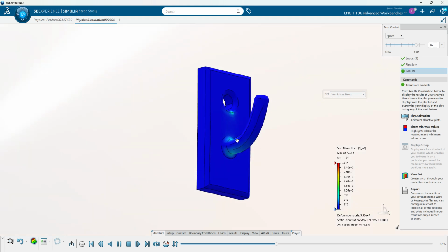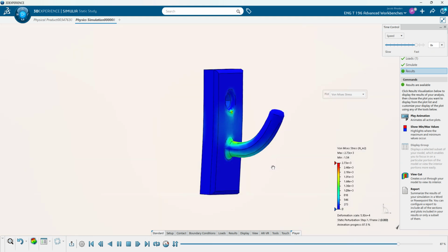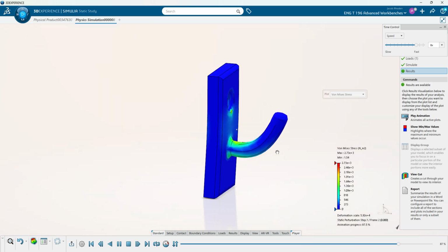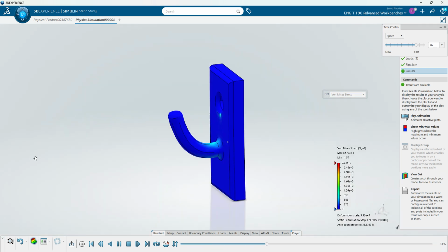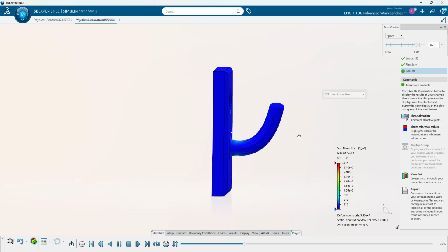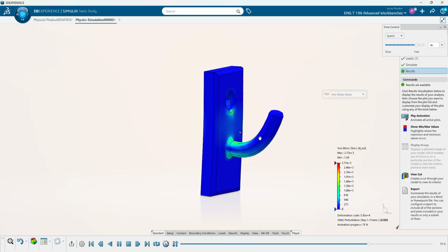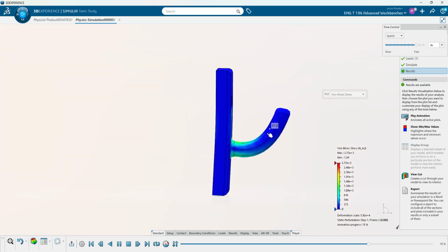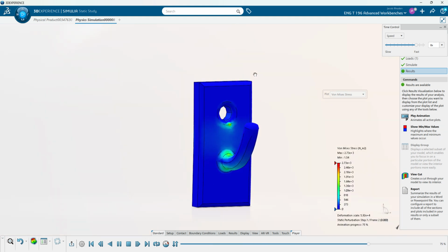So now we have to think about, okay, how can we change this hook to make these stresses, these parts of the part body deform less? And now obviously there's a lot of options. You could thicken certain pieces, you could change the way it's being held, maybe changing the location of this hole could stop the whole overall body stress, the overall kind of forces pushing this back. So we will show you that in part 2.